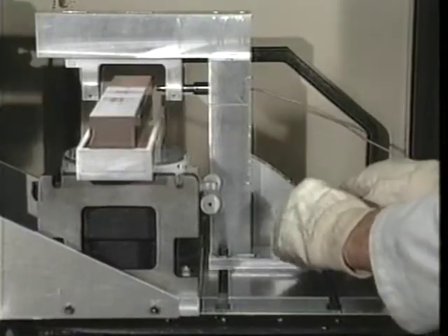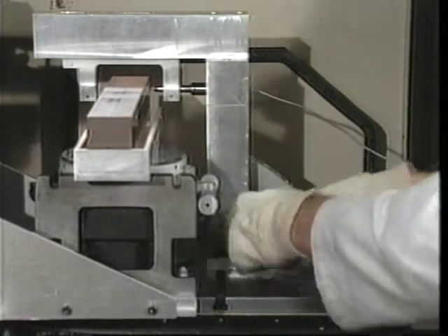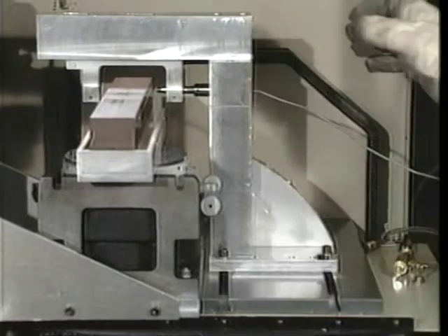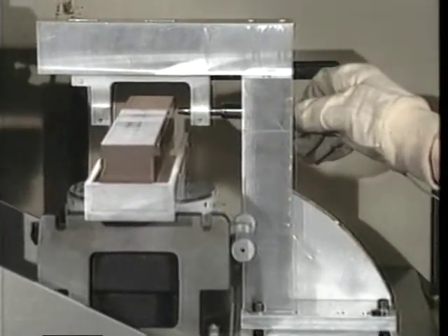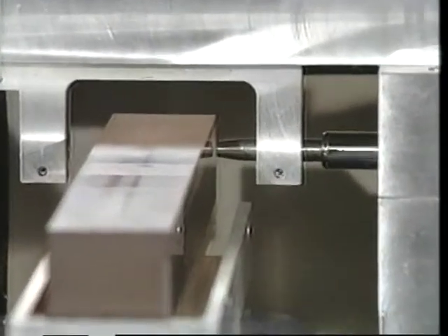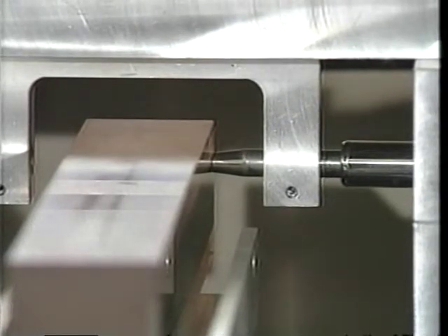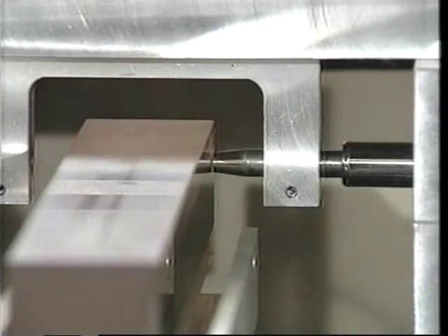The capacitance gauge is mounted to the x-axis slide such that it probes the reference surface of the straight edge. The capacitance gauge will measure the lateral motion error of the moving slide and the irregularities in the reference surface. As you recall, the non-contacting probe will sense changes in the separation of the probe tip and the reference surface by measuring the changes in the capacitance of the target area on the reference surface and the sensing area of the probe.